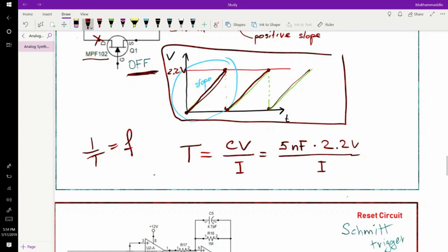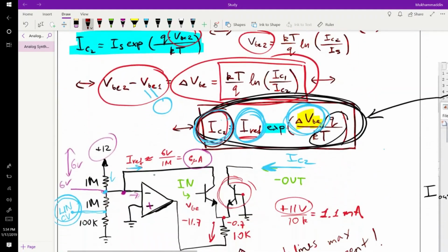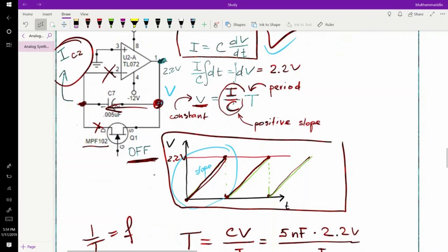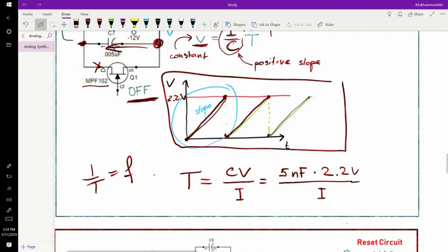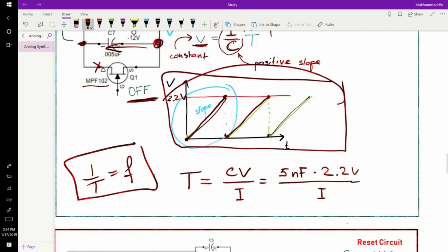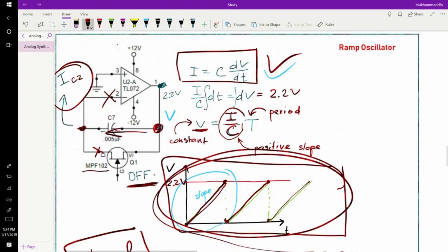By controlling our voltage using the knobs on the front panel, we first reduced that to a ratio of 18 millivolts per volt of change on the front panel. Then using that, we converted linear changes in voltage into exponential changes in current. Using that current, we set a certain frequency for our oscillation, in this case, this ramp waveform.